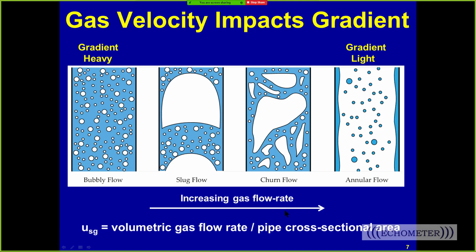All right, so this is getting into something we call flow regime, and we're going to talk a little bit about what we call the transition. The transition is where we use Turner to determine whether the well is liquid loaded. Here we're liquid loaded, and liquid is accumulating because the velocity of gas is too low, and the gradient, the change in pressure versus depth, is high, which means there's more pressure back on the well per foot because liquid's accumulating in the tubing.